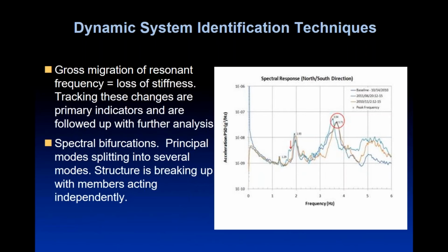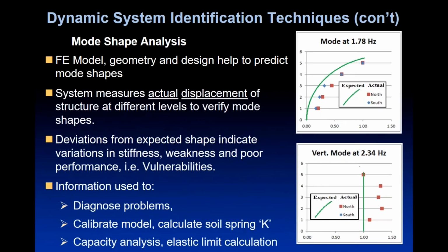So there we've separated two things going on. Just two things in this case. But we've got a third one here. We've got this remnant peak at 1.29 hertz. We've actually got what is the beginning of a mode of failure on that structure. And in practice, what was going on here was that there was a big crack in a wall, which created that as well. Not large. This is 10 to the minus 9 g squared per hertz. It's small. It's not something that you'll see, but it's enough for us to keep an eye on it and make sure that it doesn't get too big.